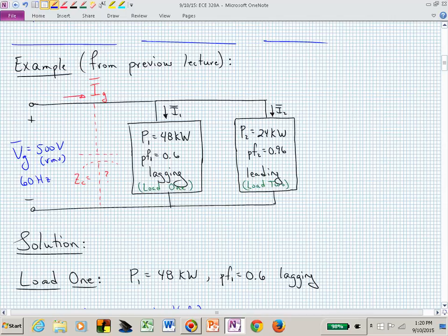And they're requesting 57 kilovars. And the capacitor is able to deliver that because they're really just complementary. One builds up and the other one is giving back. Then the magnetic field collapses and that just goes into the capacitor's electric field. You can think of it as playing the accordion. But that's the idea. You're just trading back and forth. One builds and the other one collapses, and you accommodate what they need.